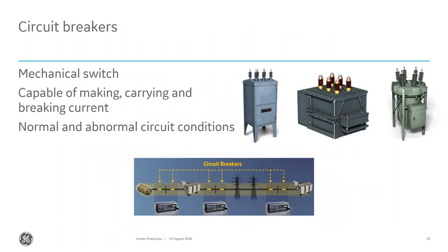Now, circuit breakers. As I mentioned, they're capable of making, carrying, and breaking currents, including exceeded amounts of current. Some of the higher circuit breakers that I've been involved with have 63 kA interrupting capability. It's a lot of current. That was when I was working in New York City, so you can tell, in such a closely connected grid, how much fault current you'll see on the system.